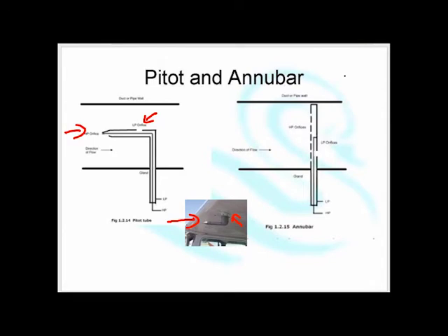So a pitot tube is used to measure velocity, and from that velocity we get flow. On aeroplanes, it gives you airspeed. Now, the problem with the pitot tube is that it only measures velocity at one single point in the pipe, which is fine if you've got fully turbulent flow, but completely messed up if you don't.